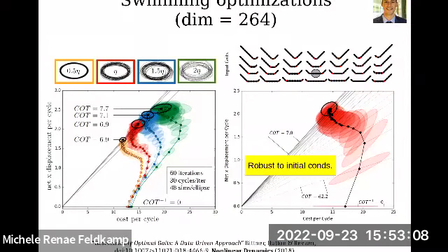So we compared optimizations under a lot of conditions, and I'll just get you to the conclusion. This is a very robust method. It's robust under choice of initial conditions. It's robust to the level of noise, even very aggressive levels of noise, where you see the noise here is on the order of a third of the diameter of the cycle. So imagine I'm taking a half-meter step and I'm off by 15 centimeters every step. That's a pretty aggressively noisy system, and this optimization still works.